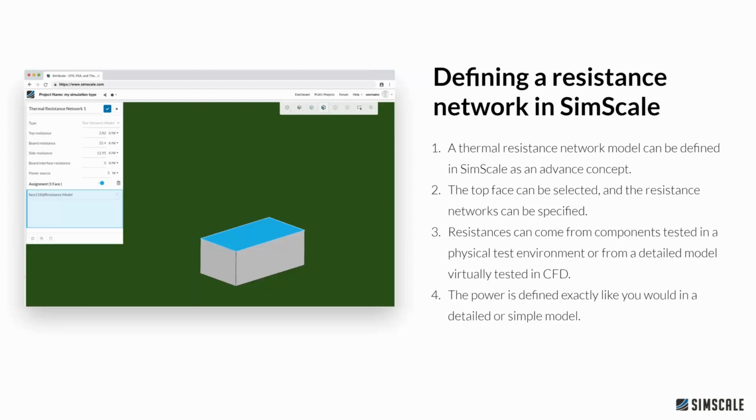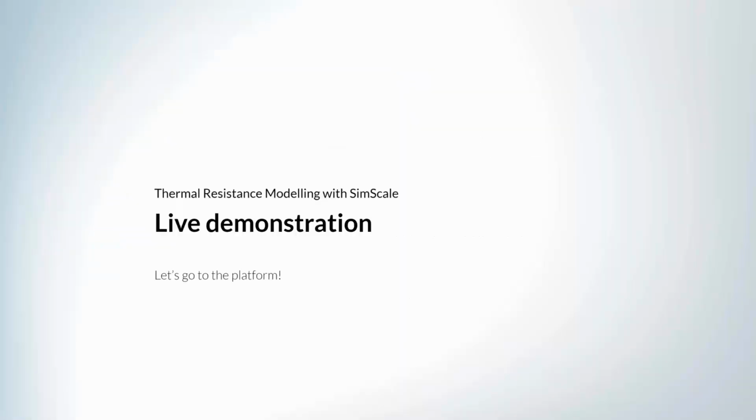Naturally, the manufacturer or physical test data is going to provide you with more accurate results because they've taken absolutely everything into account and real-life data has been used to give you your resistance model. Just in the case that you haven't got that data, which unfortunately is quite a few cases, you will go ahead and do this detailed model and use the resistance values from that.